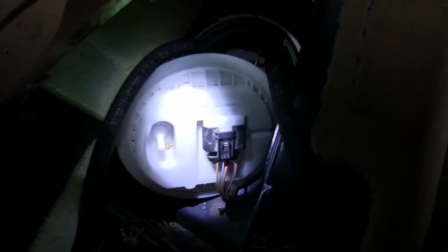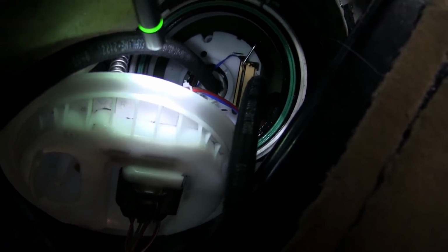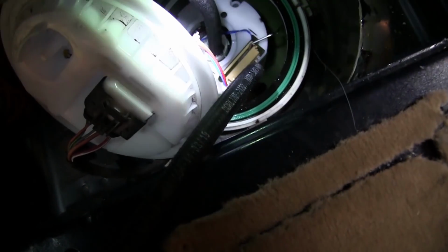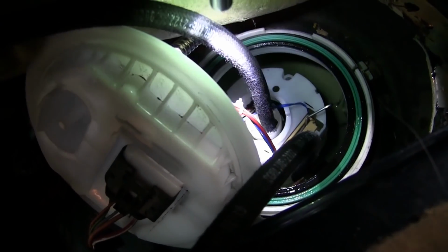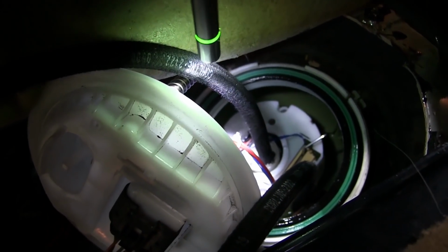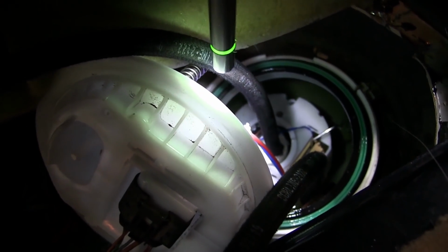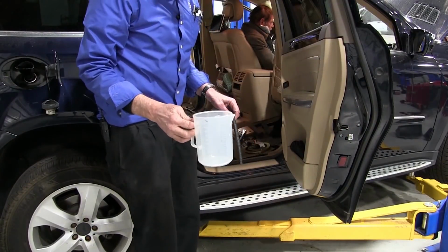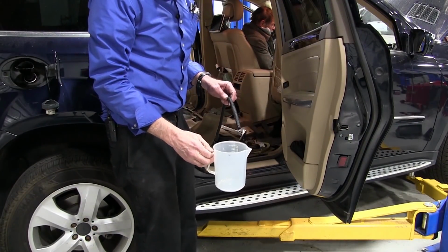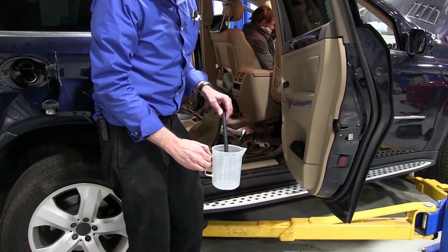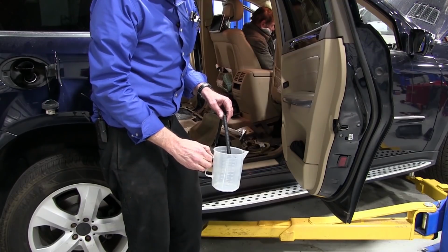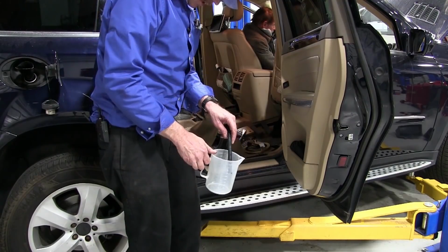Okay, so I took the top of the tank off and I pulled the crossover line off, and we've got a hose directly on the outlet of the pump right there. So that pump has now got a hose directly out, and we're going to flow it directly out of the pump. We're going to see what we got. Okay guys, so this is 1,000 milliliters, so this is about a quart. And 42 gallons an hour would fill this in about 30 seconds. Go ahead and crank it.